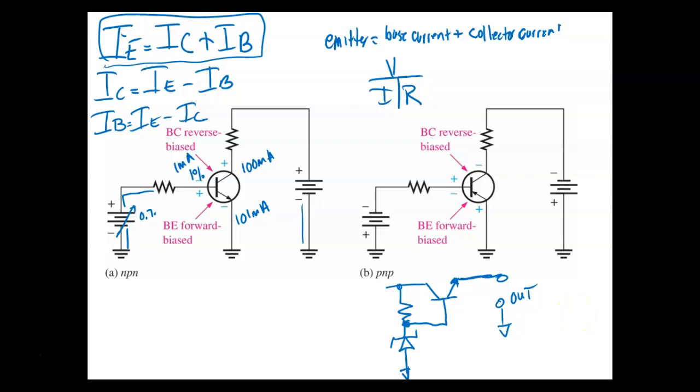So what can I get out of a transistor? This is a current valve, guys. So we get a real high watt current gain. Now, the biggest problem we have with Zener diodes is that you just can't operate at a lot of current. But what we're using here is a Zener diode to provide the base current to the transistor, and then the transistor is running the output. So over here, if this is a 5.6 volt Zener, then this guy over here would be about what? About 5 volts, but at a lot higher current.